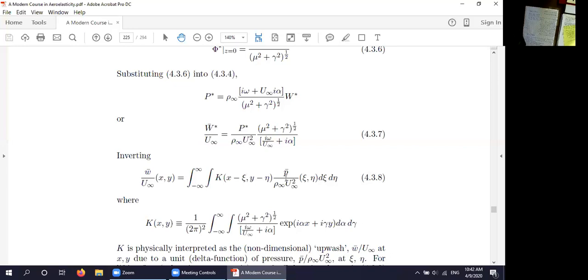So what people did originally then was to take this pressure and, rather than carving this integral up in boxes, they assumed a series solution for the pressure where each term in the series was chosen so that the pressure was zero at the trailing edge, right? Sort of satisfying the boundary condition through a modal form. And people worked on that for quite a while, and it works.